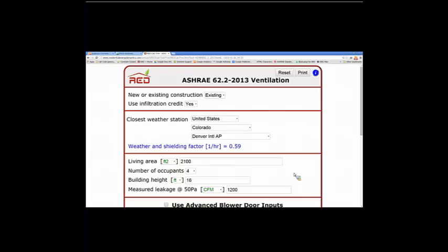So that's a fairly clear issue in the standard. Now, years ago, for I'm guessing decades, it has been in various codes, BOCA codes going way back, that if you have an openable window in a bathroom, you do not need to put in a fan. That's where we were once. That has now changed, and I think the change is a positive change.